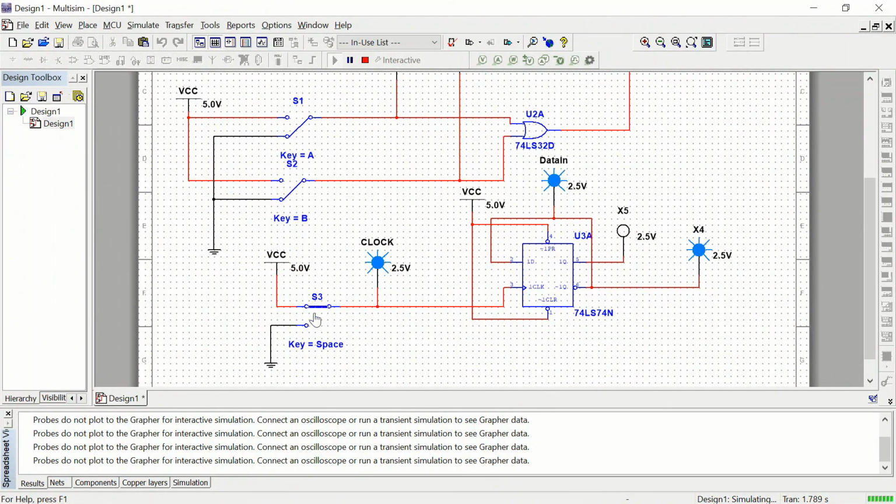And then it goes high, and okay, so you probably get the idea that with a flip-flop, you have it tied to some kind of clock. And this is what's called a positive edge trigger, but it causes the values to flip-flop, but only when the clock goes from low to high. Making the clock go from high to low doesn't change the output. And so only when you're flipping the switch in that direction do you get any kind of change.